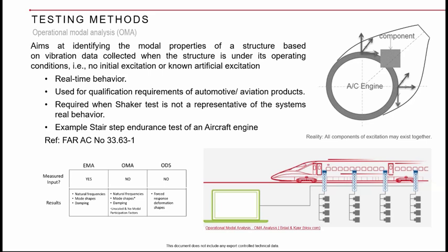So this is one thing where you can actually try to collect the behavior of the structure, its responses, or the modes of vibration when it is undergoing actual operation with no initial excitation or non-artificial excitation. So I am not trying to excite anything through a shaker, but I am just running or operating the engine. Or for example, we just discussed the rotor excitation kind of thing.